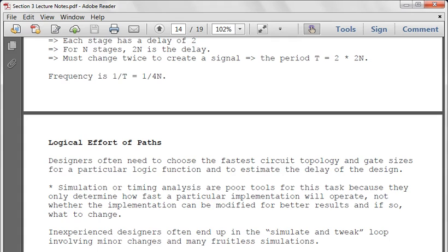If you minimize the logical effort, you minimize the stage delay of the critical path. Then, if you're trying to ensure the timing is proper, you can reduce the amount of buffering that you have to do on the other paths. If you reduce the amount of buffering, that means you're reducing area. That means you're reducing power consumption. So dealing with these kinds of issues will benefit you. Additionally, calculating logical effort paths will help you in designing circuits.